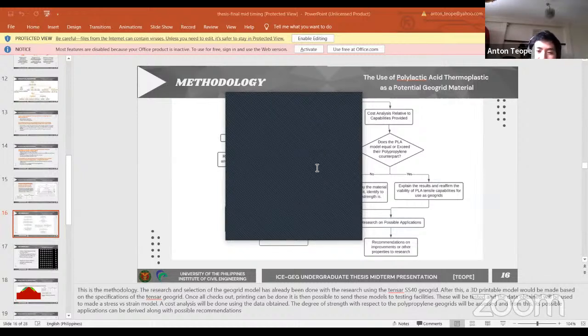To answer Ma'am Tori's question, FLAC slope has a feature of including geosynthetics into the embankment. The geosynthetics isn't really specified. However, I've seen certain researchers using FLAC slope which assume the geosynthetic to be geogrids. And since the cohesion and bond friction angle were not obtained, I chose a range that included Wulandari and Tahandra's values for cohesion and bond friction angle.